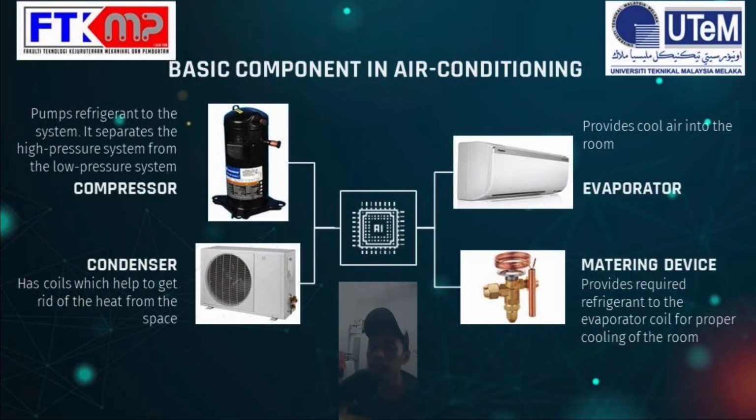The next slide is about the basic components in air conditioning. In an air conditioning system, we have four important components. The first one is the compressor. The compressor is a mechanical device to pump refrigerant through the system. It separates the high pressure system from the low pressure system.